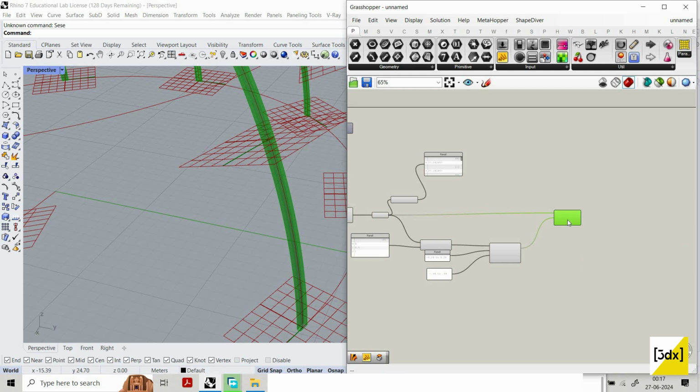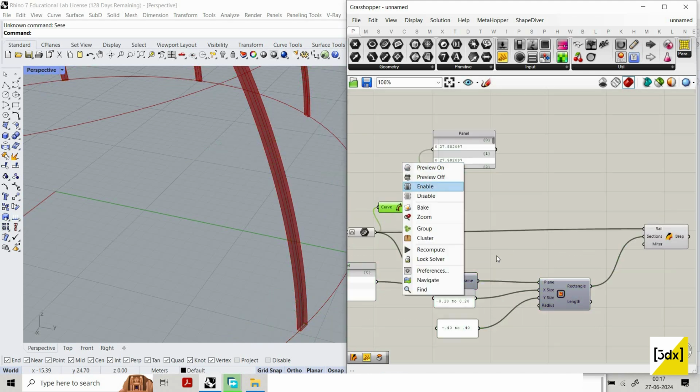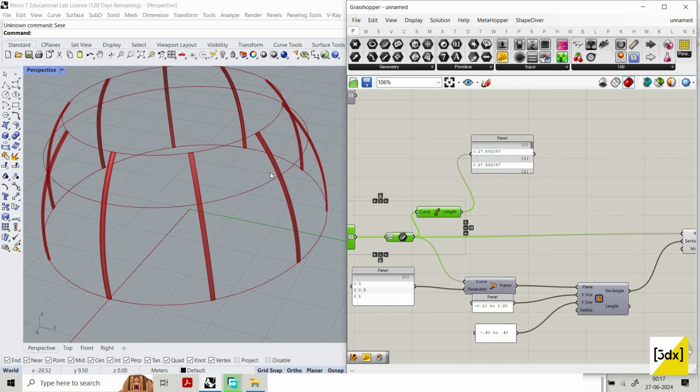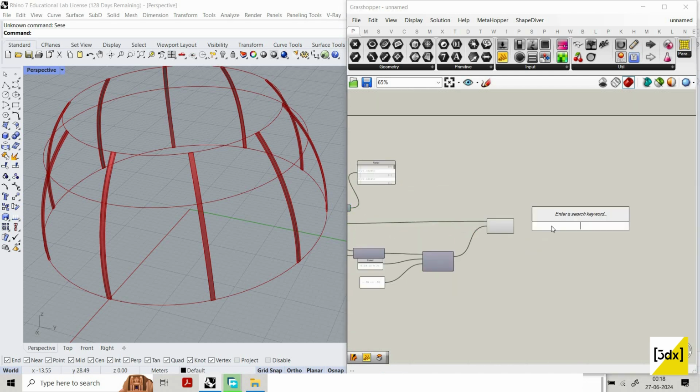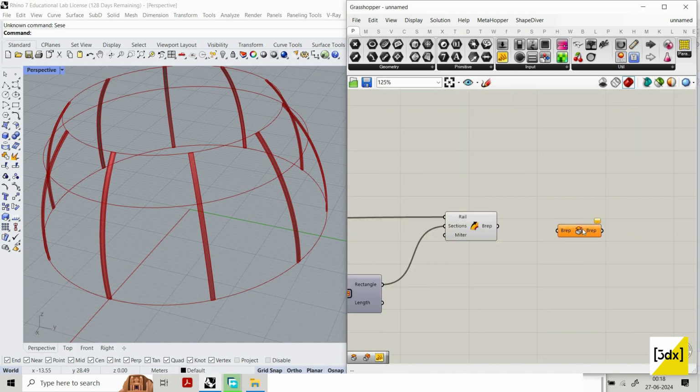You can also sweep directly. This is not a big complicated curve, but it is better to use a perpendicular frame in this case, so that you don't make a lot of mistakes. This is a perfect shape, so the value doesn't change when you sweep around the curves. So we got the sweep. Now we are going to cap it.